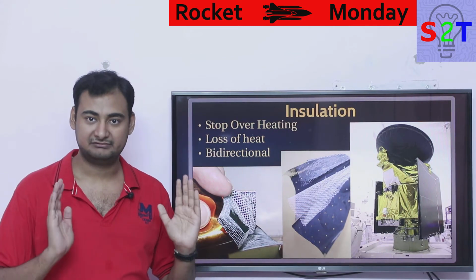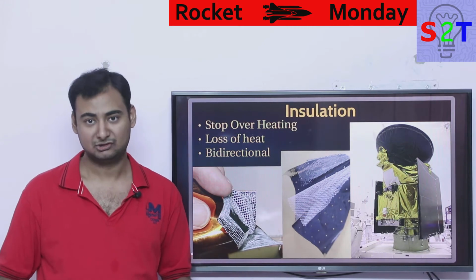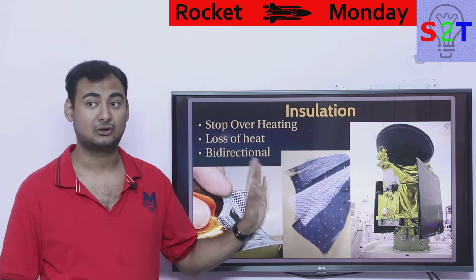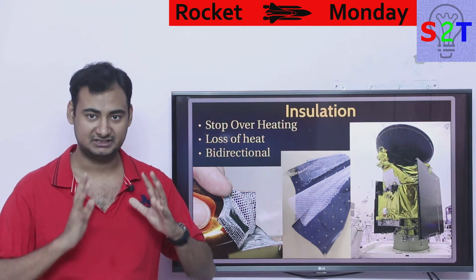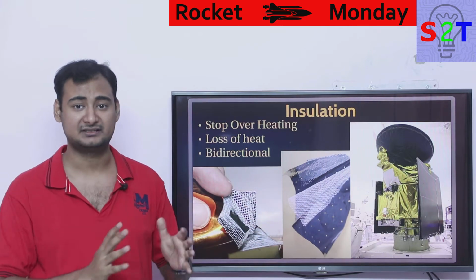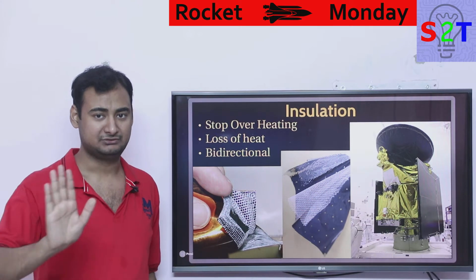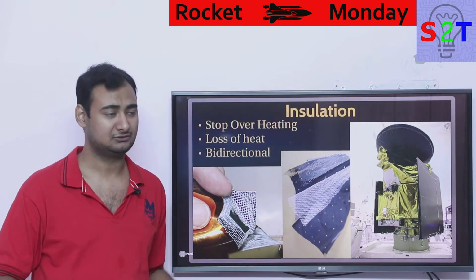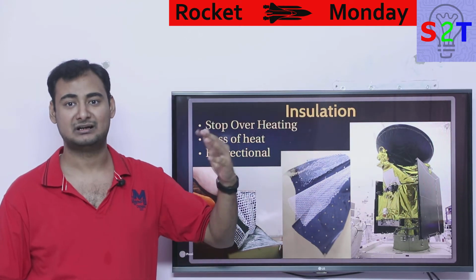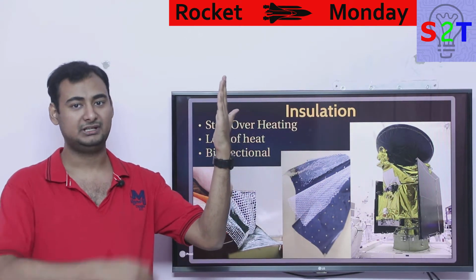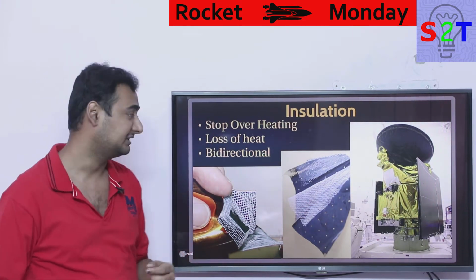If you have a limited mass, let's say you cannot put more than 10 kilos, gold would be better than aluminum. So gold foil is very good at stopping infrared, and our sun, a specific star, is very hot in infrared. It's giving off a lot of infrared. It's not giving a lot of gamma rays or x-rays, but it's ludicrously bright in infrared. So if you can stop infrared, you can take care of most of the solar energy. It's like, okay sun, I take care of your infrared. There is not that much x-ray or gamma ray that you'd put on the gold foil and still be melting on this side. That won't happen because our sun is not very bright in x-ray or gamma rays.